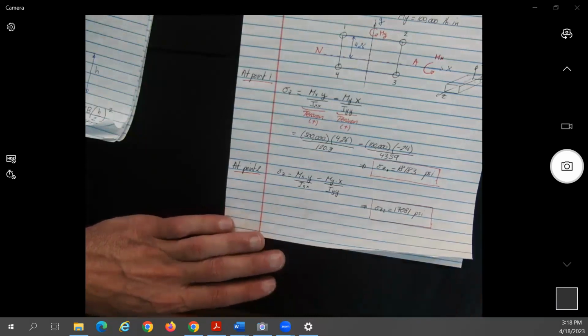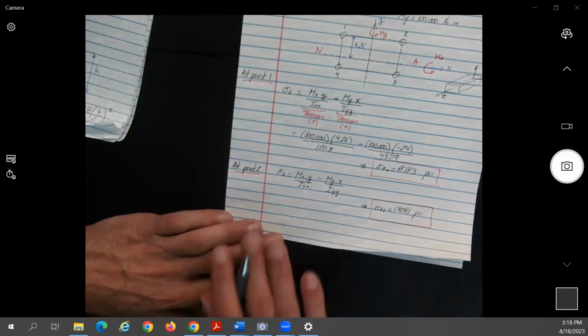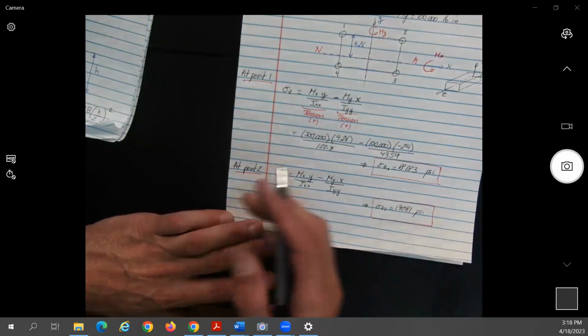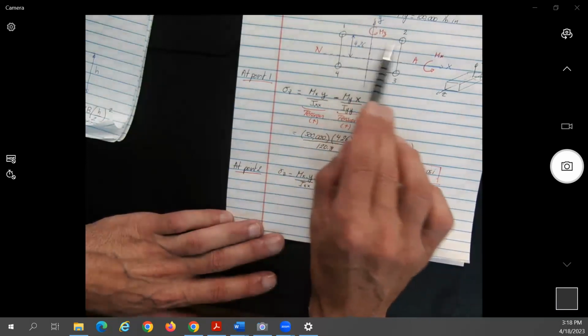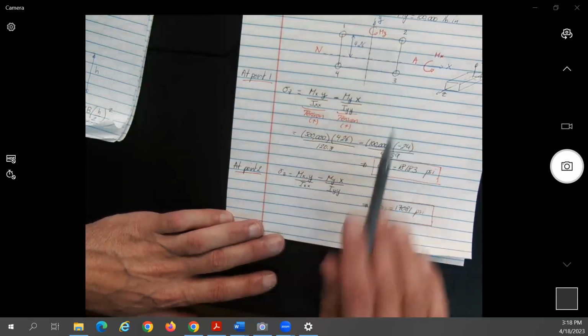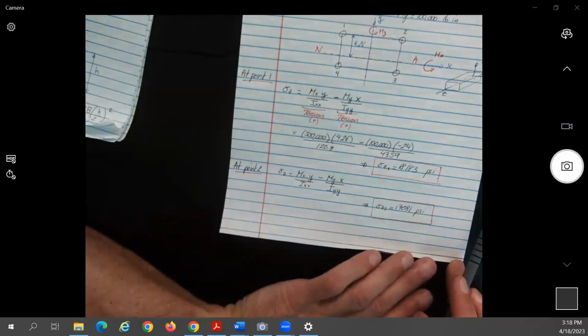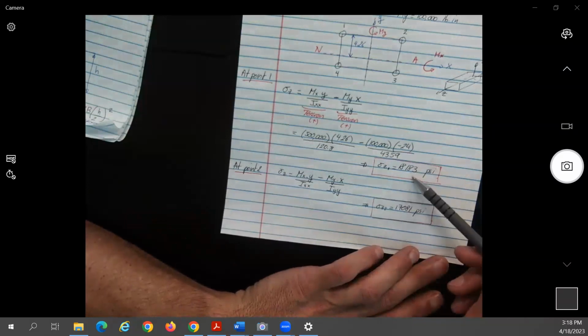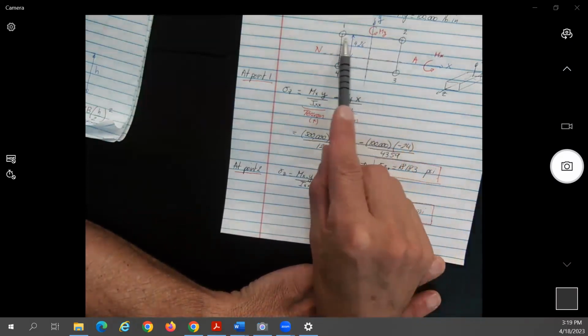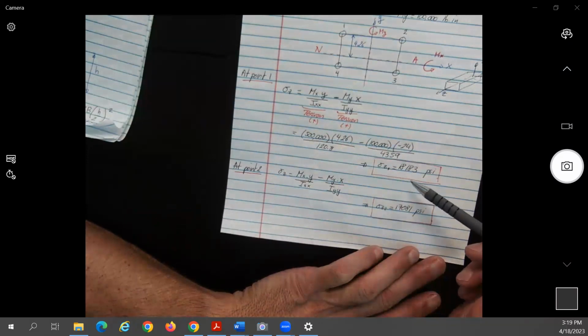So I will do a problem with you later on, okay? And we'll do that in more detail. But to tell you the truth, in real life, for example, if you needed to calculate the shear flow due to this, it's basically what we did because it's straight, no? It's basically the same assumption. What could be a good approximation of the shear? Look at this. Shear should look at the difference of these two stresses, and divide that value by the distance here, which is 48. How much?